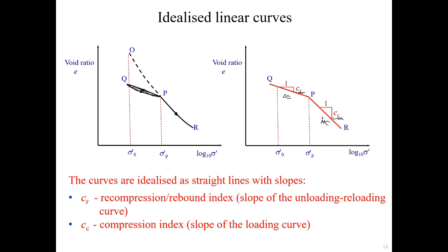What do you mean by unloading? Is that when you take the pressure off? Yeah, that's right. So you see, for real scenarios, you have some pressure, maybe out of construction. You have the Q here, and later on, maybe you gradually reduce the load or totally remove the load. Then surely you have some unloading occurring. So this will be the unloading curve. If you take the load out, then the soil will rebound. So that's what this curve and gradient represents.